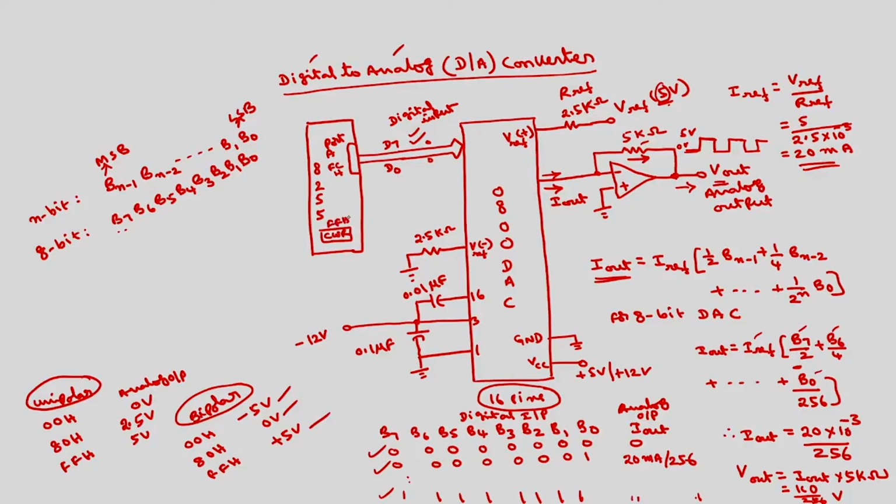So to generate the square wave, what you have to do is, first you have to program port A as an output port. Move AL comma 80H, 80H will program all the ports as output ports in mode 0, which we discussed in earlier lectures also. Then you have to out onto the control register whose address is FFH.